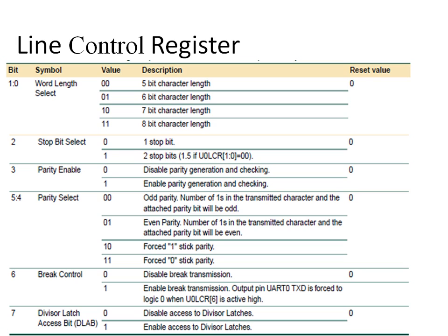Now what does a frame include? A frame has a start bit, the message bits, and an optional parity bit along with the stop bits. This complete thing is your frame. The process of adding the start or parity bit as well as the stop bit is nothing but framing. So the output of the framing process is your frame.